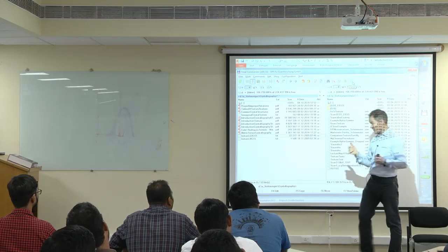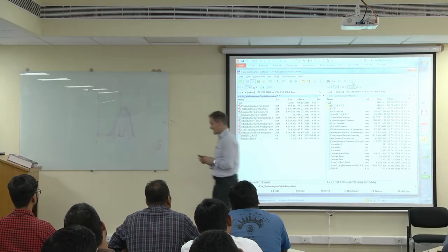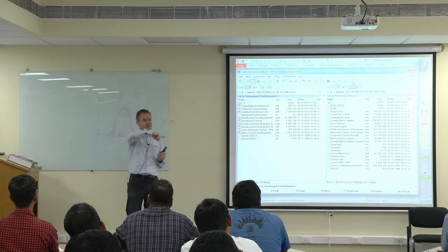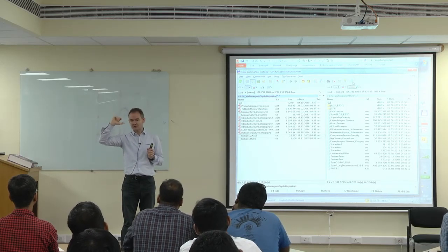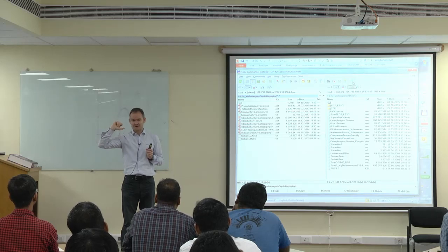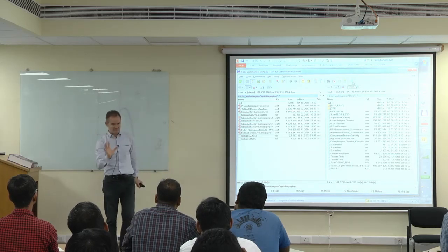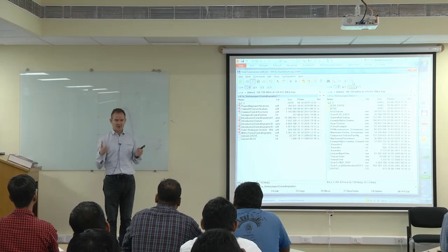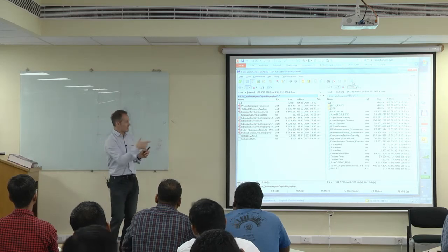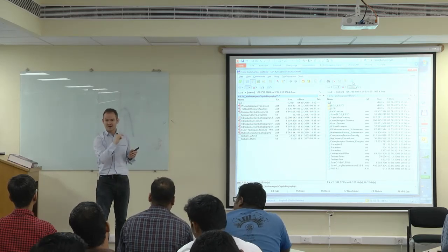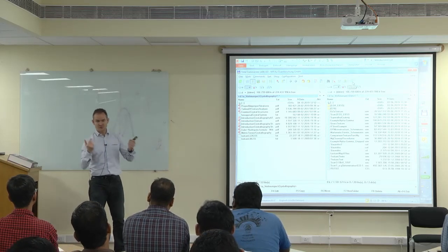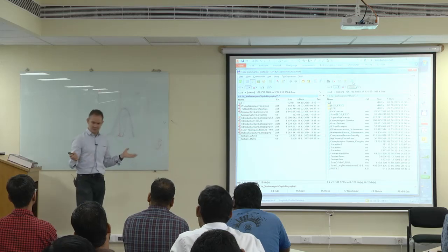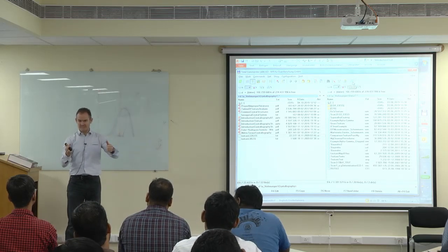We measured ourselves on DP steels in this case, and we found you get really an approximation to the real texture only after 10 to 50,000 measurements. So you need to test that, how many orientations you need to measure and how high you have to develop them before you get a proper and true description of your texture. I cannot even give you really a number now,